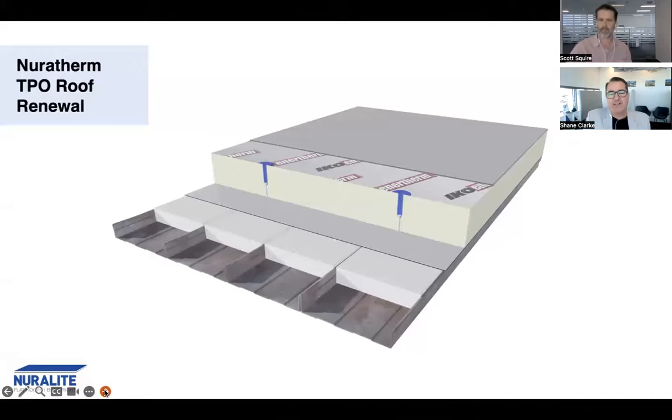So what we're looking at here in this slide is just a close-up or a cross-section of that Palmerston North roof build-up. So we had the existing standing seam metal tray, which we then placed some insulation infills in between to bridge the gaps. We then ran our continuous aluminium vapor blocker across the entirety of the surface of the roof.